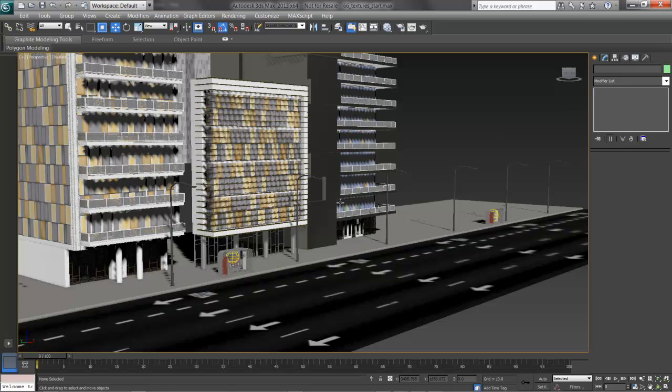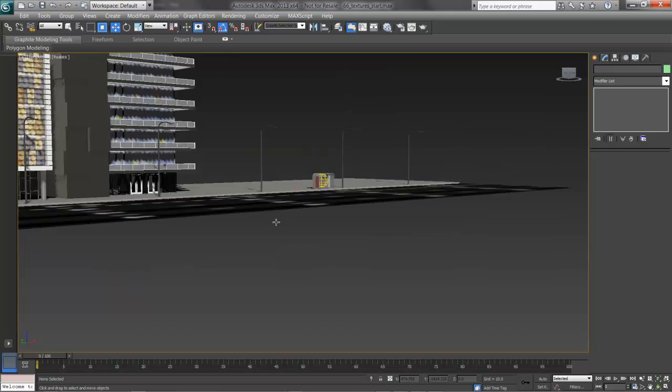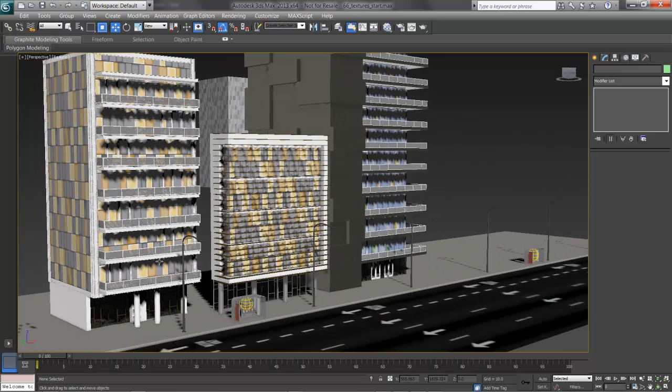I've added in textures in the same way on a lot of the buildings, using images I drew in Illustrator and Photoshop to define what looks like lit windows. They're a pattern that repeats, but has an overall pleasing effect when we back out. Additionally, what I've done in mapping is to map each of the floors of the buildings, such as building 1 here, slightly differently, so we don't see the same lit window in the same place. And I did this just by moving around that gizmo in the mapping, using a UVW map in the same way I did the road.